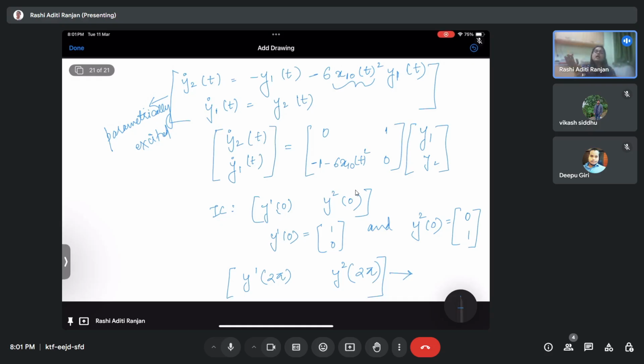Then we came to the concept of a parametrically excited system. For the parametrically excited system, we introduced the Floquet theory, on the basis of which we said that the system was either stable, or unstable, or having a periodic solution with time period equal to the time period of the parameter term, or twice of it. And now we use the same Floquet theory to predict the stability of a periodic solution. So essentially we were just talking about an equilibrium point, but now we are talking about the periodic orbit.